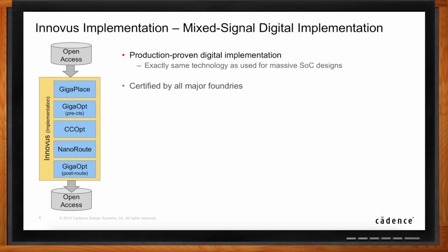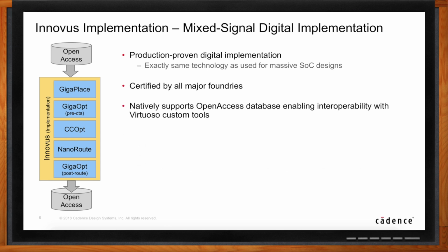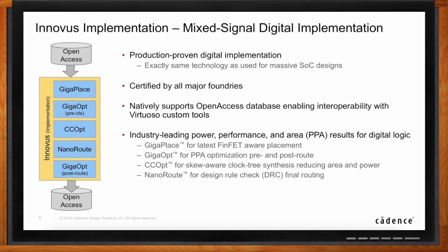Nice. So they don't have to feel that they're using legacy old technology, and therefore everything that we can do in our regular place and route flow based on Innovus is going to be accessible to the mixed signal designer. Now this is very important because earlier on we talked about power optimization. You have to do significant power optimization during the implementation of the digital portion. Even if it's not super timing critical, it will certainly be power sensitive. So we firmly believe in ensuring that all the power optimization technology in Innovus can also be available to the mixed signal designer.